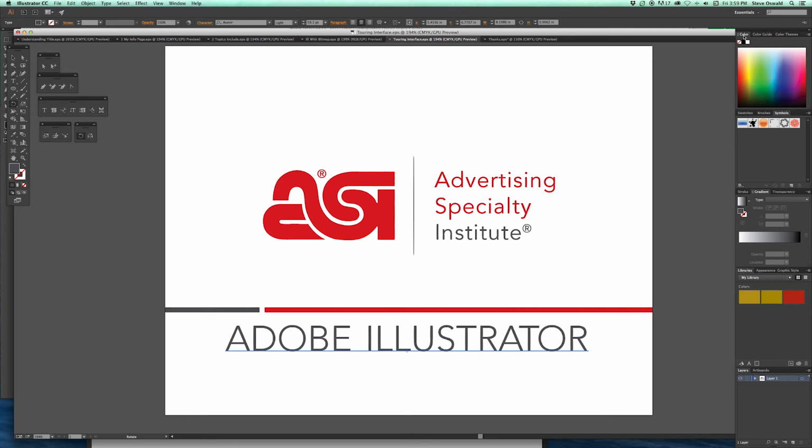If we're interested in the color palette, we can click and hold its tab and drag it out and free float it within the page. If I want to put it back, I simply just drag it and bump it back in. You see the blue highlight on the outline telling me it's placing it back into this group. If I want to move its position within that tab, I just drag it straight across and bump it where I'd like.